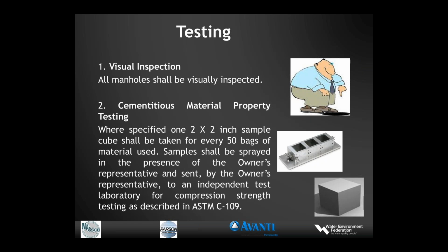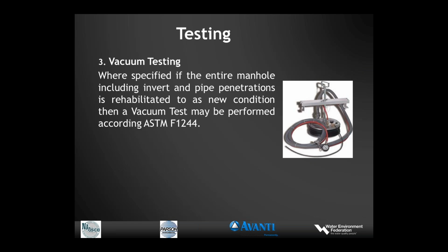And like I said, it's not a cube or something that is just handed to the inspector. It actually has to be poured from the material being installed into a mold. You can see the typical mold. You have here one with 3 spots in it, and to give you an idea, on the bottom right is where the cube has been taken out of that, and that's used for testing. That's typically for cementitious.